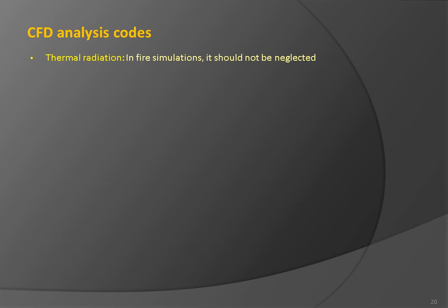In fire simulations, thermal radiation should not be neglected. The simplest approach that I have observed is to reduce the heat release rate of fire. Initially, FDS utilized such crude method, where the fire heat release rate was reduced by 35%.